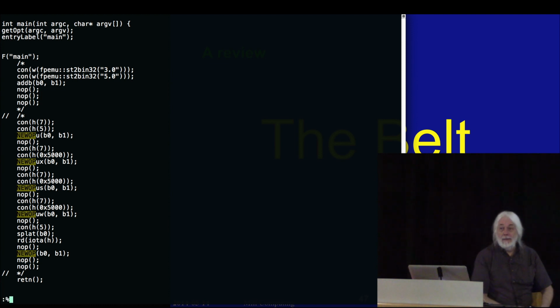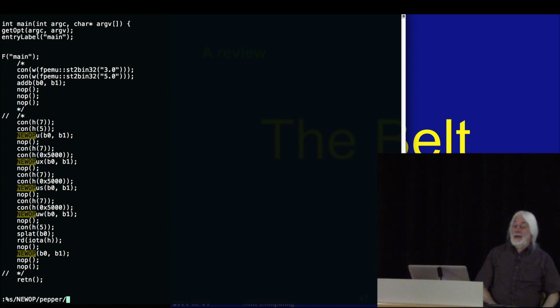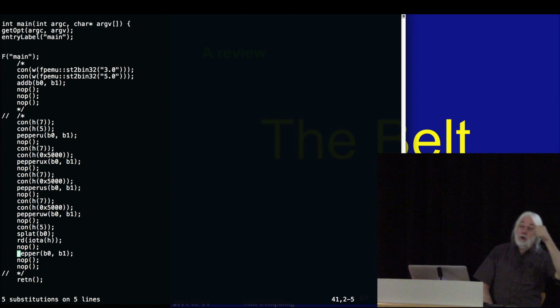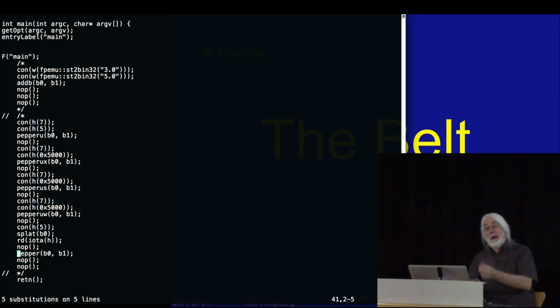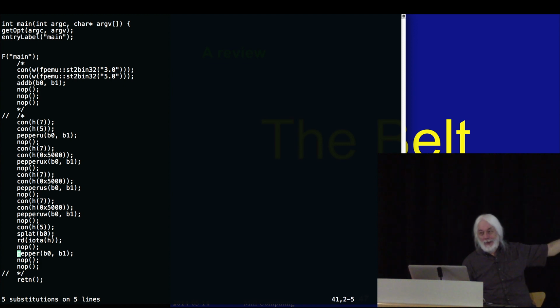Where does the return command return? The return here at the bottom? Yeah, that is a final operation here, and if we'd actually executed through it, the simulated hardware would have detected stack underflow, would have attempted to assert a hardware trap, would have discovered that the trap vector was not initialized, and would attempt to do another hardware trap. That in turn would wind up into a system hardware trap, and at that point it will simply bail out and power down the machine. Yes, we do simulate all of that. I have not bothered showing it to you.